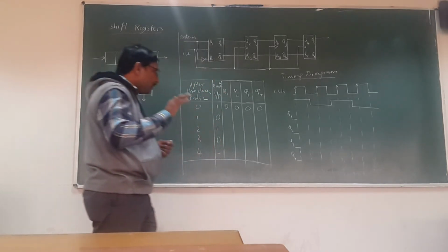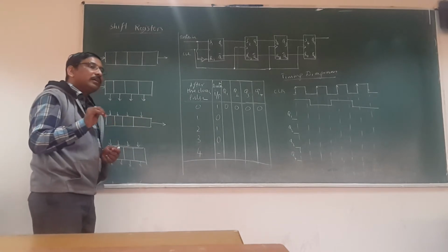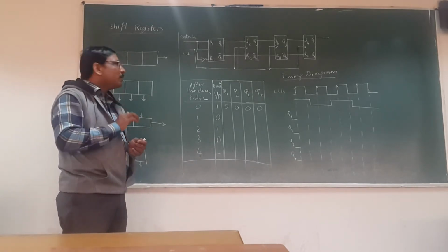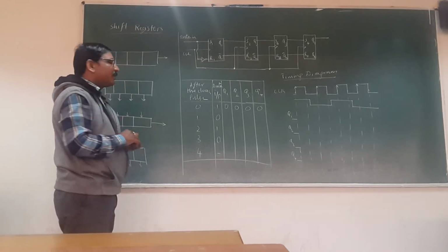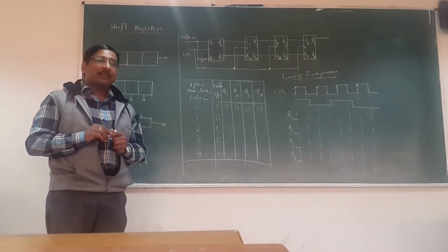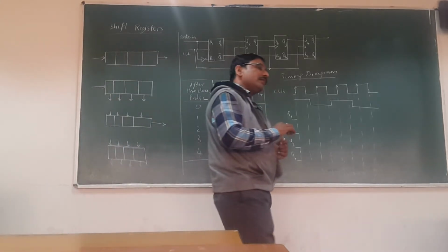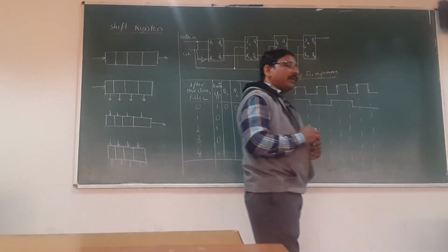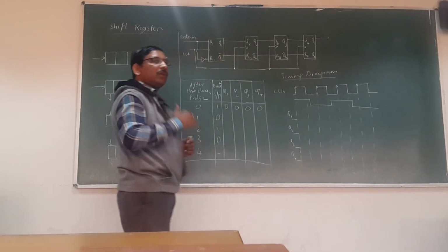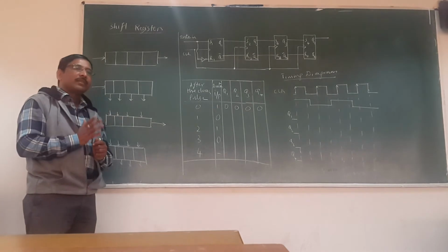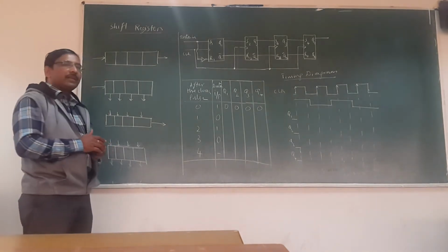So right now, what is the register? It is a group of flip-flops used to store a group of bits. And we call these shift registers because we can transfer the data or shift the data inside the register as well as outside the register, to shift the data from one register to another register, register to memory, memory to register and so on. So these are the shift registers.